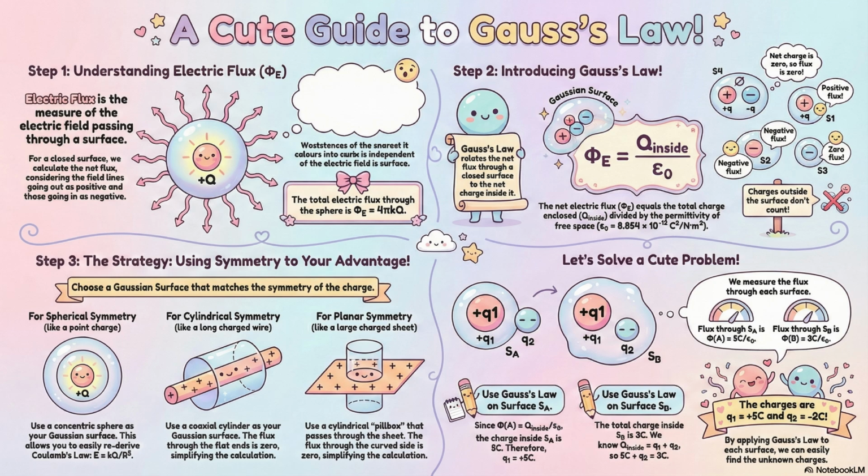Let's focus on the first two. High ESR. That's just that I squared R heat we talked about. Yeah. It's just a tiny resistor in series with the capacitor. Exactly. It generates useless heat, which shortens the component's life, but it also limits the capacitor's ability to do its job, like shunting away high-frequency noise. If the ESR is too high, it's just a poor filter.